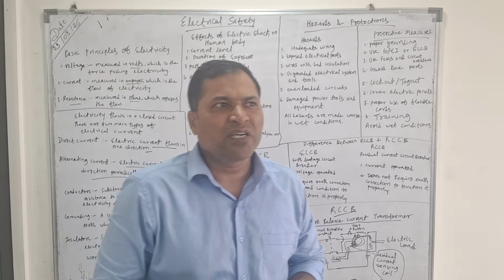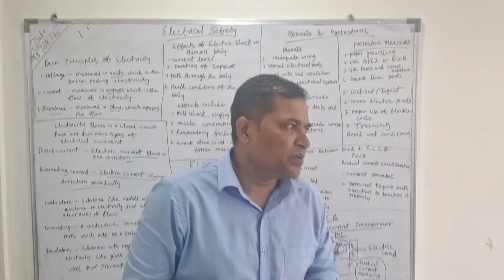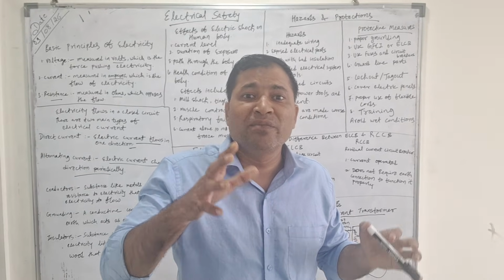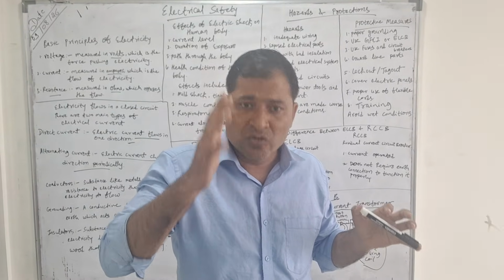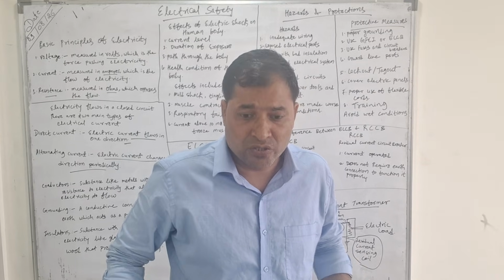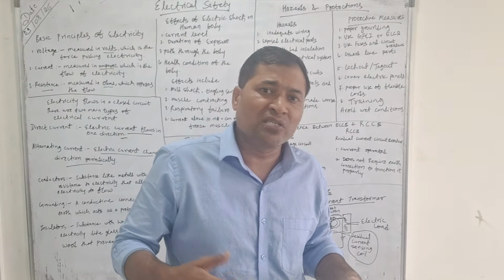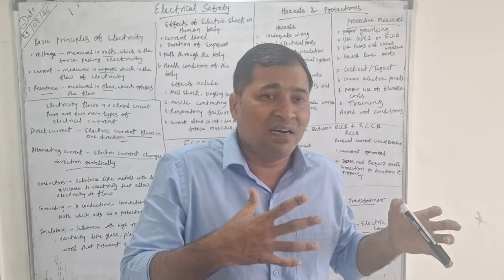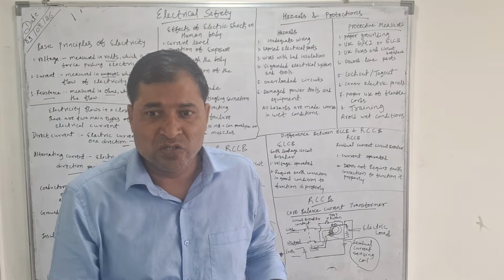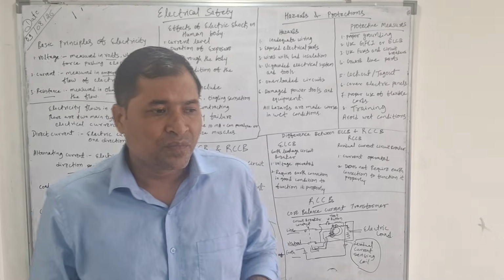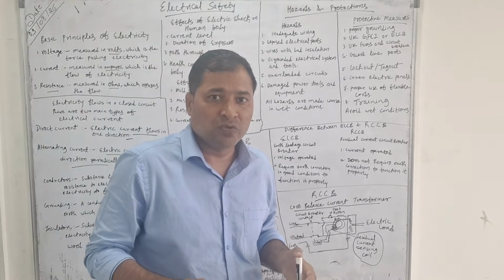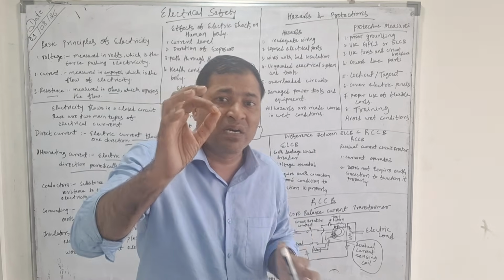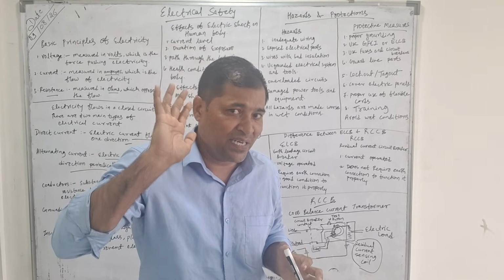Okay. For protection purposes, it is very important to always go with proper PPE. Proper PPE means helmet, gloves, goggles and shock resistant shoes. Shock resistant shoes are available in the market, so if you are working on electrical wiring, it is better to wear them. That kind of electrical shock proof PPE you need to wear. Always use rubber gloves; they are very important when you are working in electrical conditions.